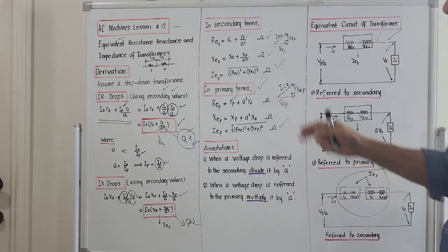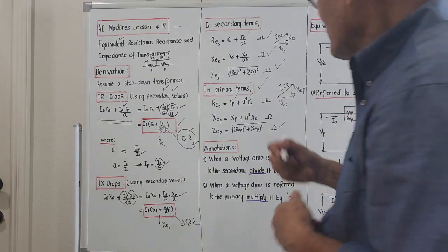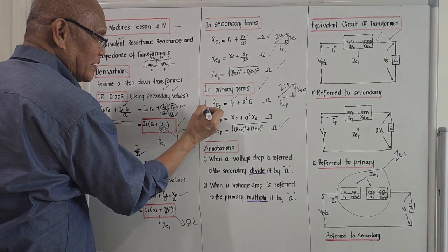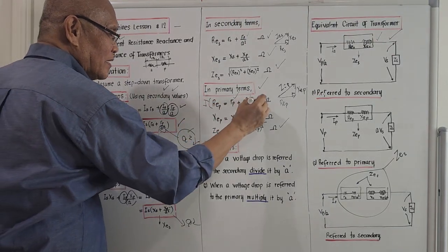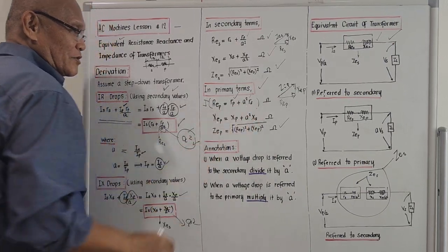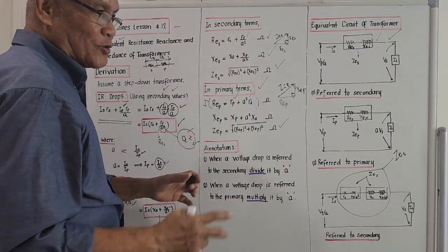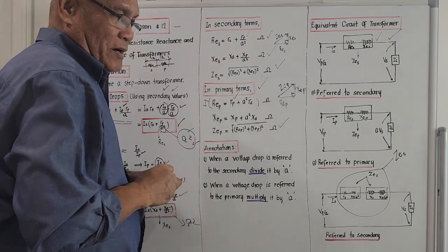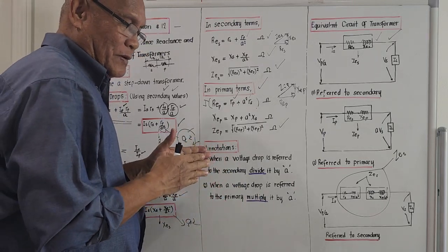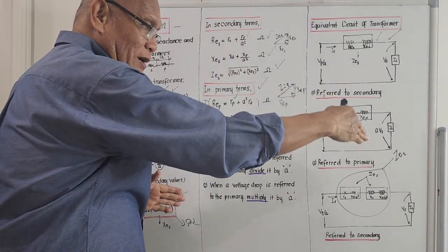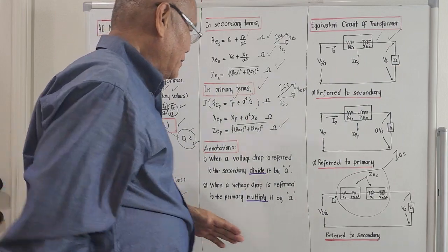If we multiply this by current, this is now voltage drops, right? So these voltage drops are to be added to the primary voltage to attain the required secondary voltage on the secondary.